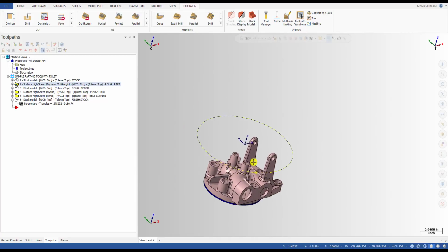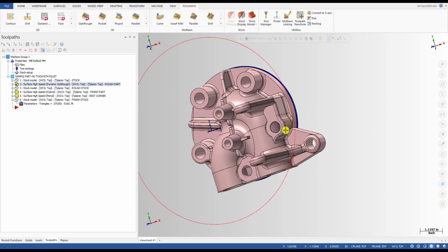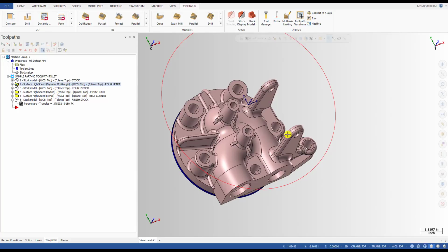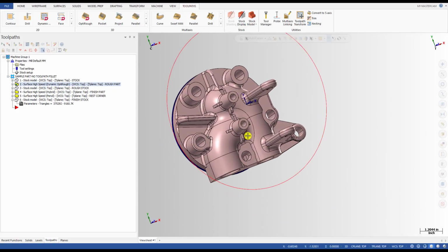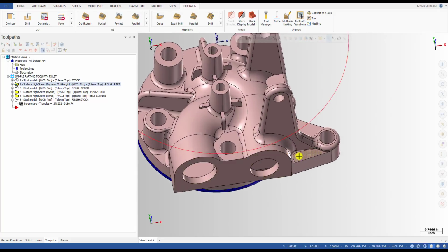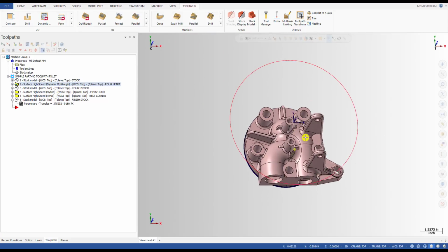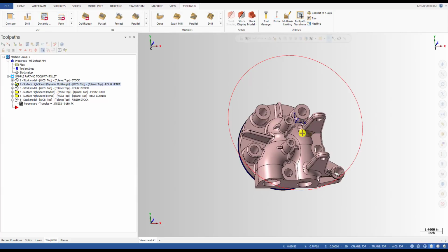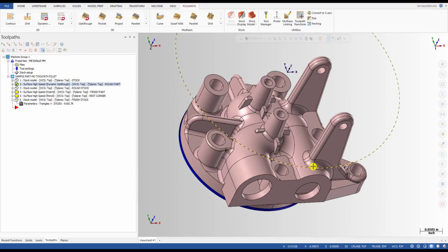But as I say, for some features like this part, the external surface here, all around, all the surface outside, maybe it's not so important, just cosmetic or something, so you don't need to run this corner and use a very small tool, because when you use a very small tool, it tends to have vibration, chatter, and everything. And a long tool is very difficult to get to the bottom of this part using a normal tool on a 3-axis machine, so it's almost impossible, and it's not so good. So in some cases, the design of the part allows you to use a bigger tool to finish this part.